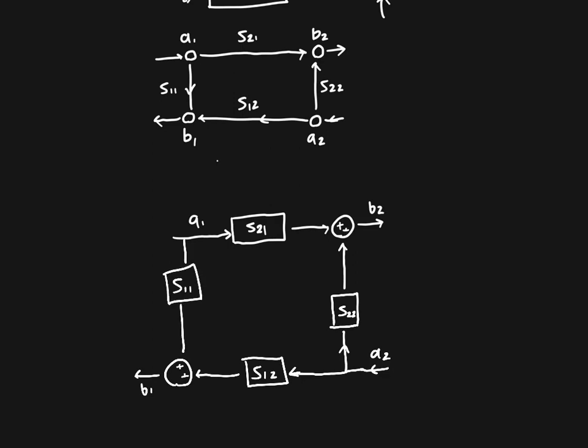And that's all signal flow graphs are. They're exactly equivalent to block diagrams. They're just a more convenient way of writing them. So we can use all of the rules that we've established in analyzing block diagrams to analyze signal flow graphs because they are quite literally identical.